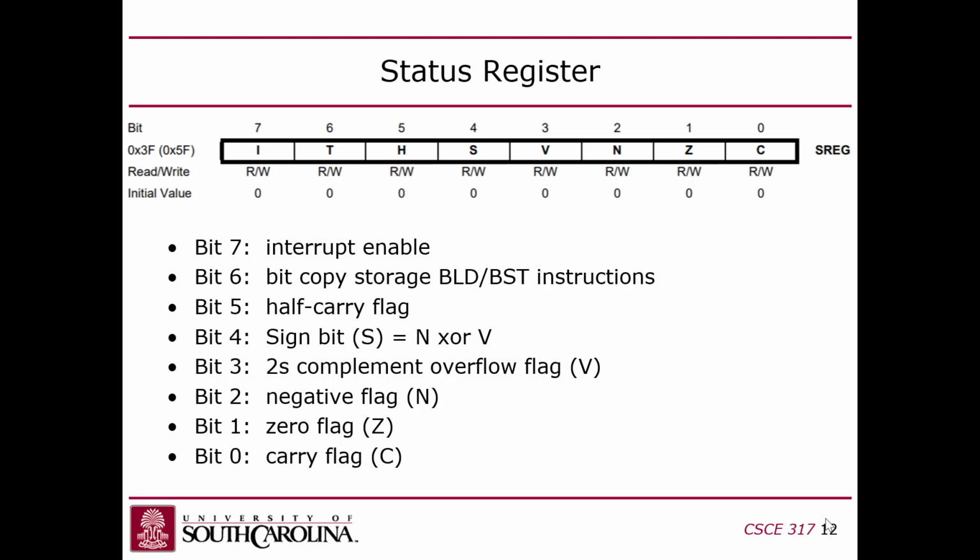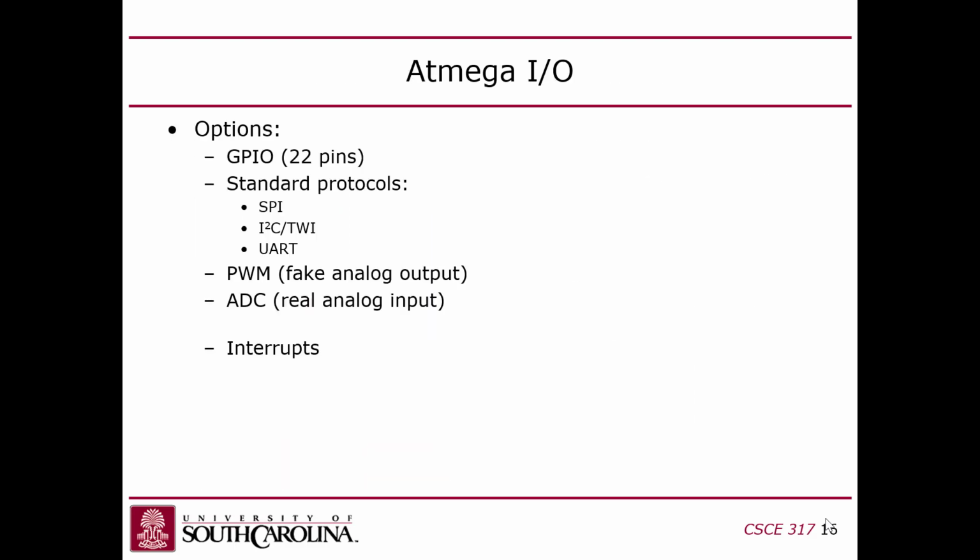But the problem is that to figure that out, each peripheral has its own interrupt enable in its own control register, and it's completely non-standardized across all the control registers. So it's very difficult to get a global picture of which interrupts are currently enabled. But luckily, the board will disable all of the interrupts by default. They'll all be turned off by default. So unless you turn one on explicitly, even if you turn on the global interrupt flag, you don't have to worry about the interrupt firing because they're all disabled by default. You guys with me? Okay, so let's show you an example of this.